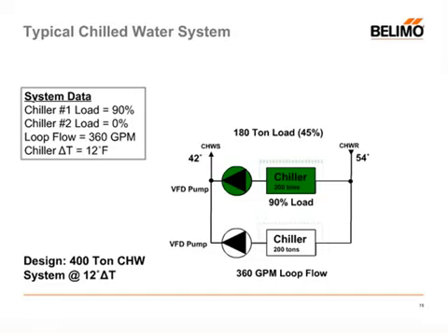Your energy efficiency has just gone way down because you're running a second chiller because of this increased volumetric flow due to the low delta T, which you shouldn't have to be running. So you're running this additional pump and additional chiller, and this is the reality. This is actually what happens out in the field with everyone's chilled water systems. At part load, they end up running multiple chillers they should not have to be running.